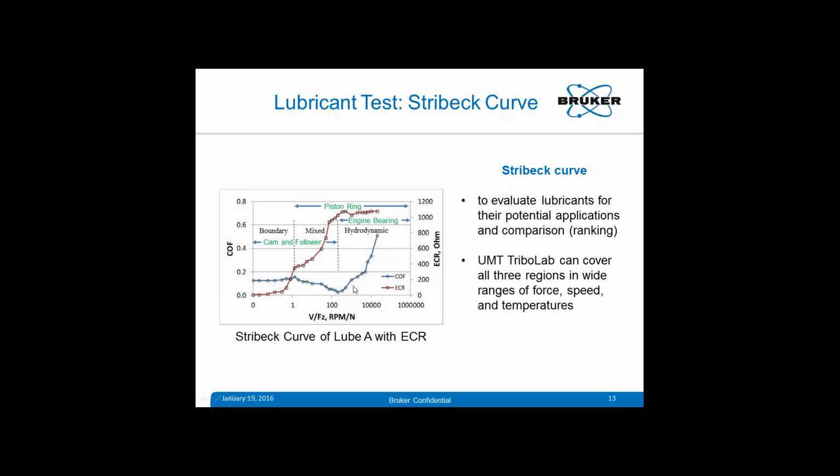At higher values it rises. At lower values it also rises a little bit. And in between there is a minimum. So this curve actually shows three different regions. One is the boundary region, where these friction couples are always in contact. Then mixed, where there is intermittent contact. And hydrodynamic, where a thick film of lubricant is present between the two contacting couples. In the hydrodynamic region, COF increases because of the viscosity of the lubricant, whereas in boundary condition, there is really wear taking place between the two surfaces.